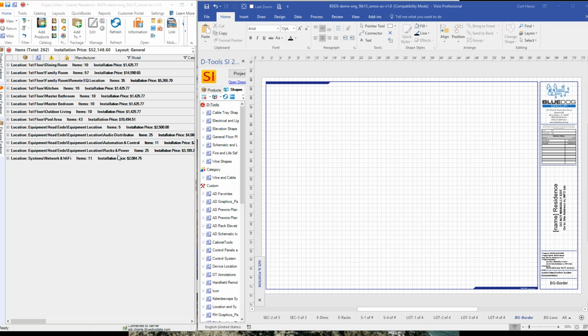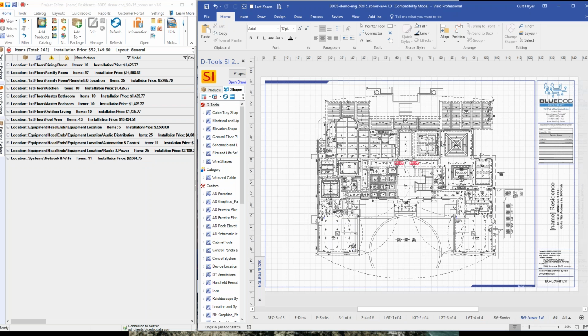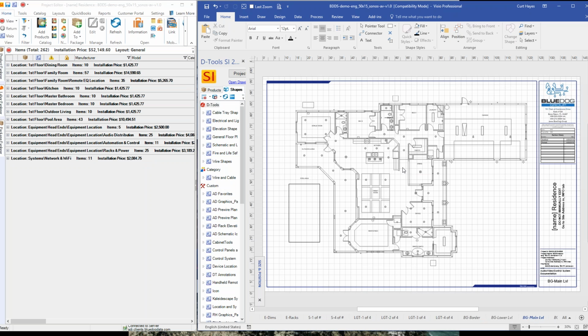And this Visio drawing is what we call pre-tabbed. So basically what we do is we set up a background. So if you look in the Visio tabs, I'm going to assume that there's some experience with Visio. If not, I probably would ask that we do hold those questions for later. But basically what we do is on a background page, we set up the border. And then what we typically do, because background files are generally large, they're image files, we'll clean up the plan view outside of DTools. We do that in Adobe Illustrator, AutoCAD, things of that nature. And we just create a WMF or EMF type file, image file, that we import as a background.